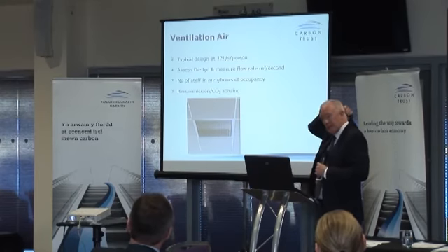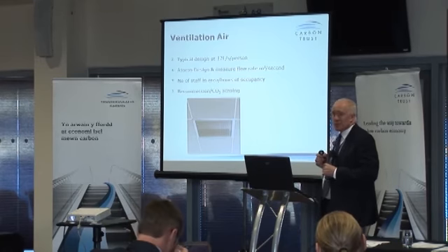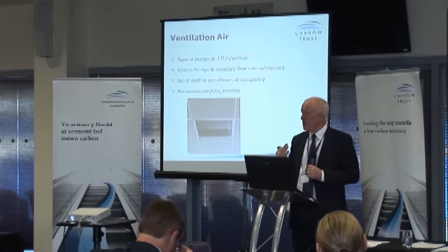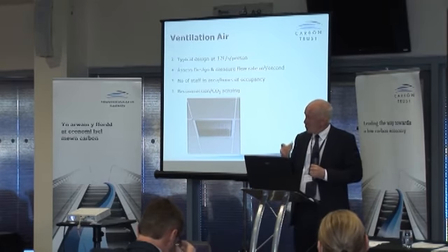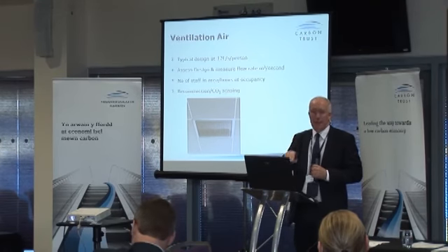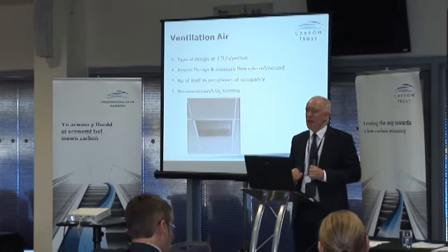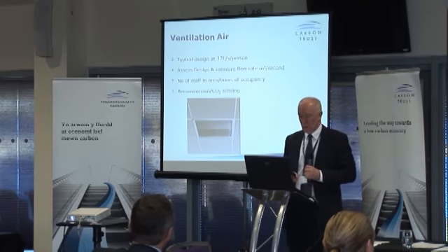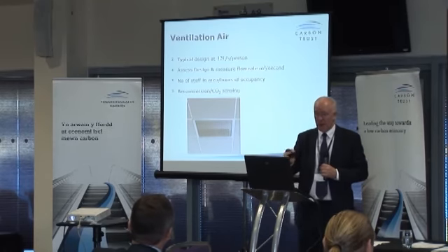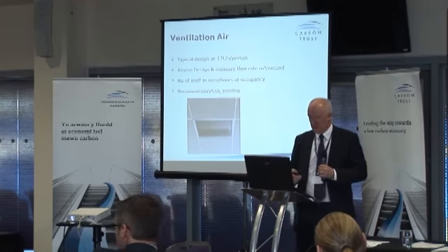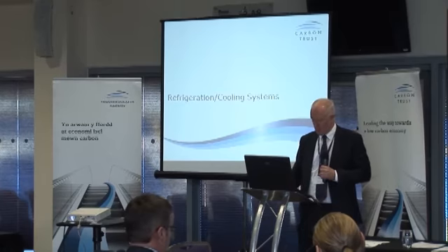Ventilation air. Typically we design ventilation to these rooms at about 12 litres per second per person, pushing in full fresh air all the time. But of course these areas are not occupied very often. You know, during the night there's nobody there, for example. So do look at how many people it's been designed for, measure the ventilation air and reduce it to as low as possible. This is bringing a heat load in all the time from outside. We can operate this with a variable speed drive from CO2 sensing if it's a large data center, for example. So again, it's a small area, but worth thinking about.